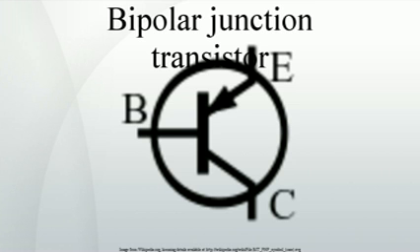Logarithmic converters. Because base-emitter voltage varies as the log of the base-emitter and collector-emitter currents, a BJT can also be used to compute logarithms and anti-logarithms. A diode can also perform these nonlinear functions, but the transistor provides more circuit flexibility.